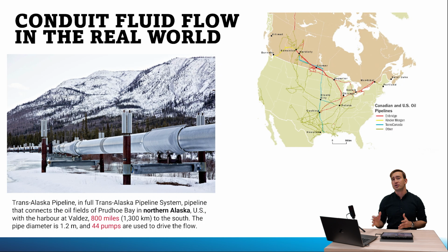Reynolds number can be calculated using the equation shown here, and you can see that using different fluid mechanics iterations of formula, we can make lots of different forms of the Reynolds number equation. The most simple one is the one that's right here, which is our VD over kinematic viscosity. Essentially, this just relates to the velocity of flow in the pipe, the diameter of the pipe, and the viscosity of the fluid that you're working with.